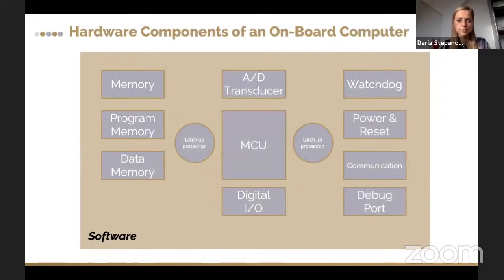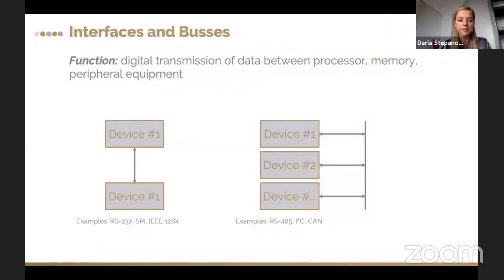These are hardware components of the onboard computer. In the core of the system, we have most of the time a powerful microcontroller with a set of digital inputs outputs to control either switches or something else. There are several blocks of memory, program memory, data memory, and general memory, which will be protected from the latch-up. There's also the watchdog, power and reset, communication, and debug port modules in the onboard computer.